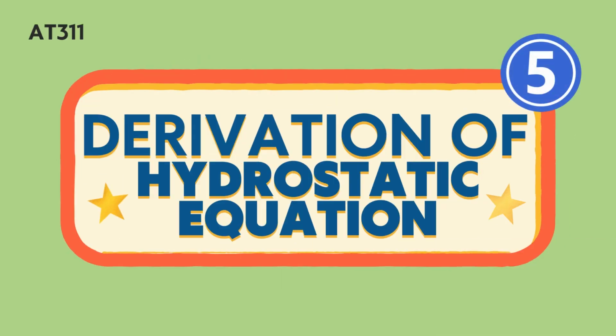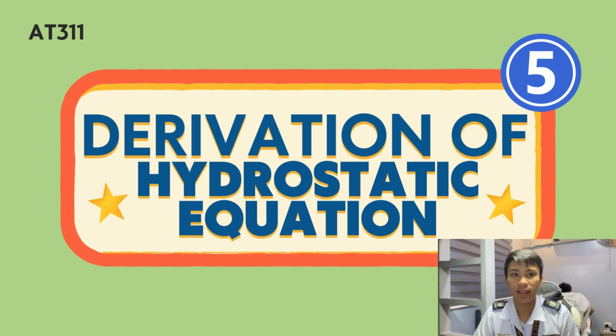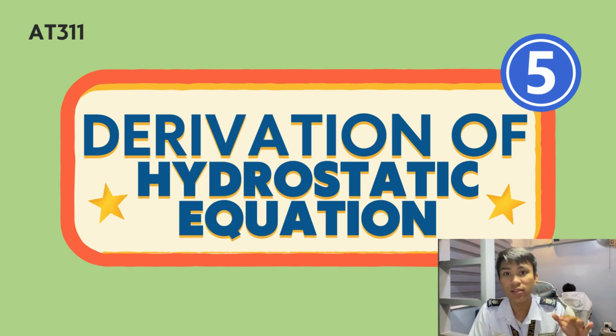Number 5, derive and interpret the hydrostatic equation. When we talk about the hydrostatic equation, it refers to the relationship of pressure to the altitude or height. In terms of the hydrostatic equation, we assume that there is a state of equilibrium because we are analyzing a fluid such as air at rest. Be reminded that all forces that are upward are positive and the downward forces are negative.